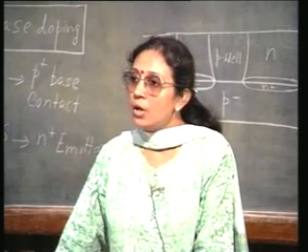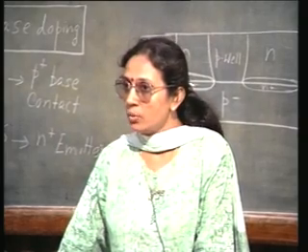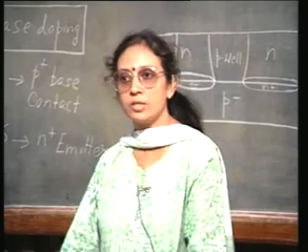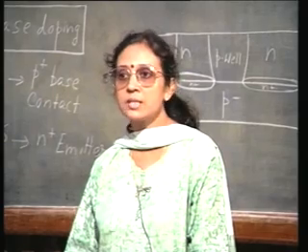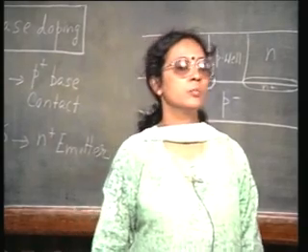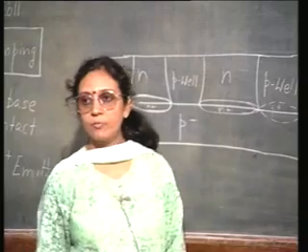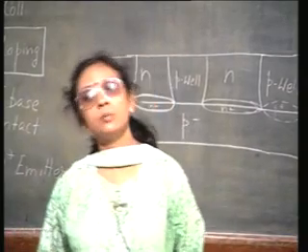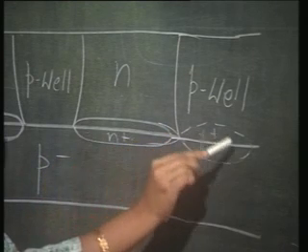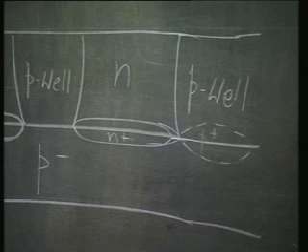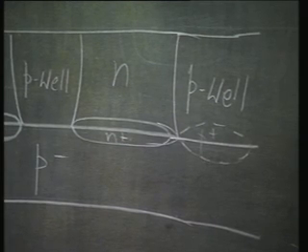Okay. But now we want to achieve greater packing density. We have enhanced the performance of the bipolar junction transistor, and we now want to put in more bipolar junction transistors. We want to increase the packing density, and in that we found the bottleneck is the low doping of the underlying substrate, because there is a possibility of punch through. So, we say fine, let us add one more step. Just like we had N plus buried layers, let us also have P plus buried layers, so that the punch through problem is reduced and we could have better packing density.